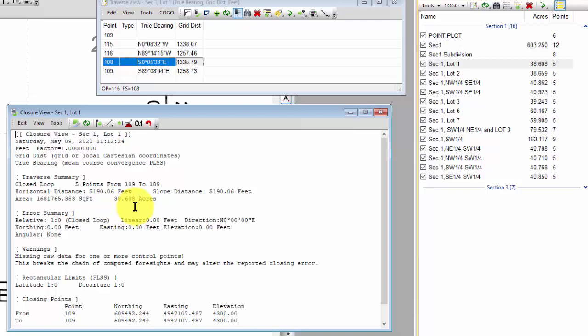38.608. Oops. I remember I talked about in the first webinar, part 1, that the BLM Manual of Instruction in the 40s, 47, said since we're working in planar coordinates, we could do a compass rule adjustment on a lot like this, and that would account for what's called apparent misclosure. Apparent misclosure is the error I get if I do planar computations around this aliquot part.